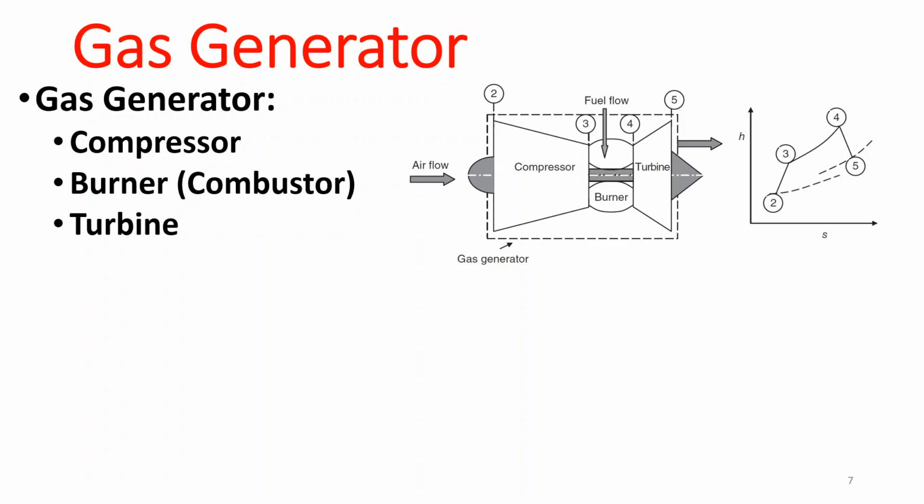I also thought, usually in the diagram, doesn't 2 go straight up to 3? Okay, that's a good question. So it means that entropy is not constant here, right? So in a real world compressor, not an ideal one, we don't have an isentropic process. It's just an adiabatic process, right? And that essentially means that, as Ryan mentioned, in an ideal case, you want to go from 2 straight to 3, right, without adding any entropy to your system.